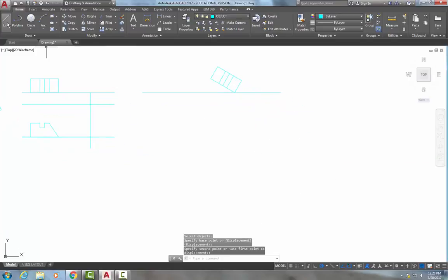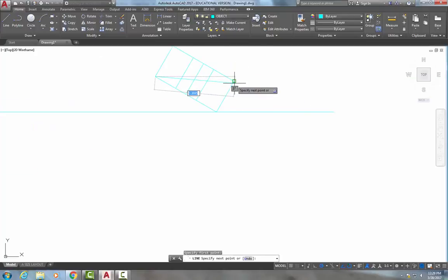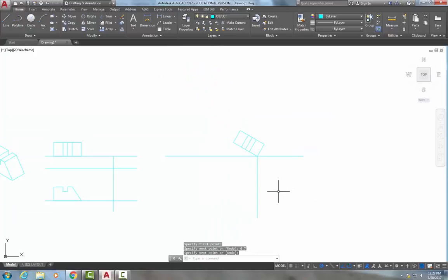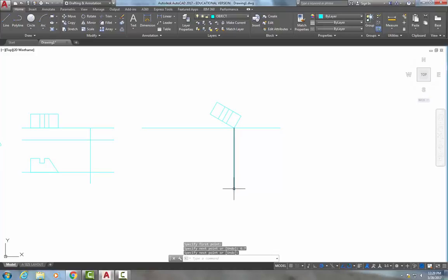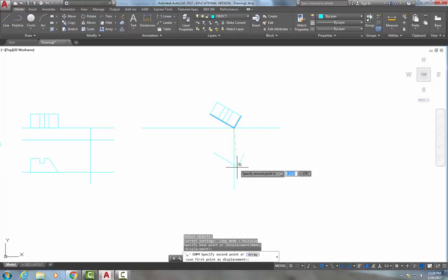And I'm going to go ahead and once again get my width. So my width now is a little different because of how I set it up. It's about 3.35. I'm going to double that for my vertical line, so 6.7, to go ahead and get my station point. Once again, I want to copy these 2 angled lines, which is how I find my vanishing points. I'm going to copy them down there.